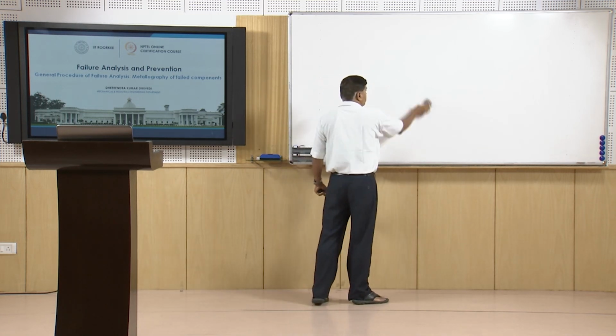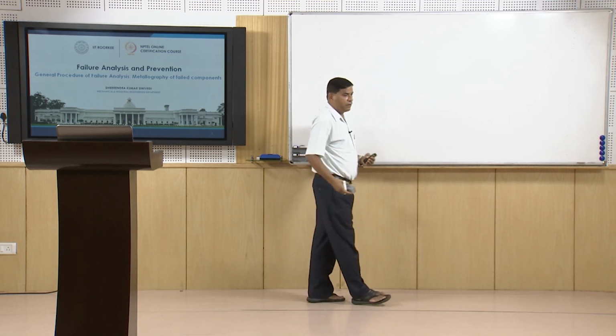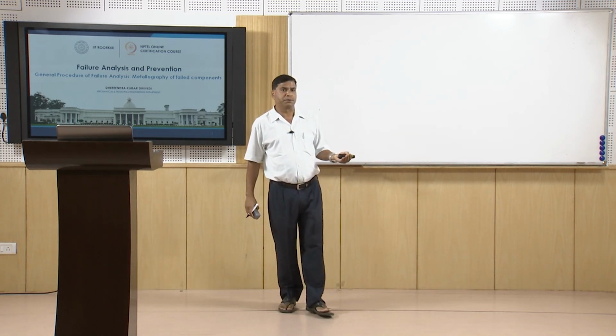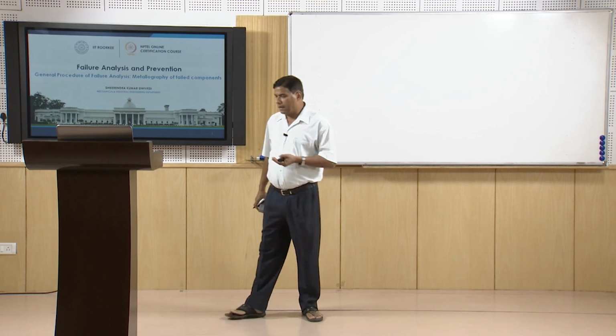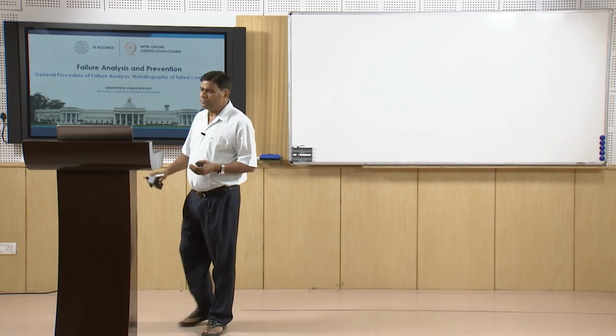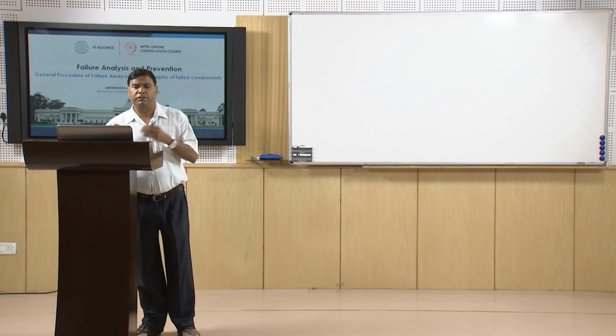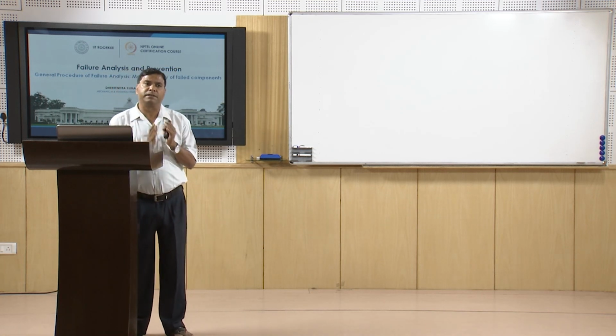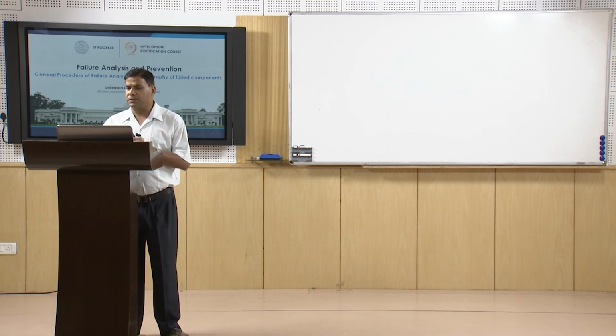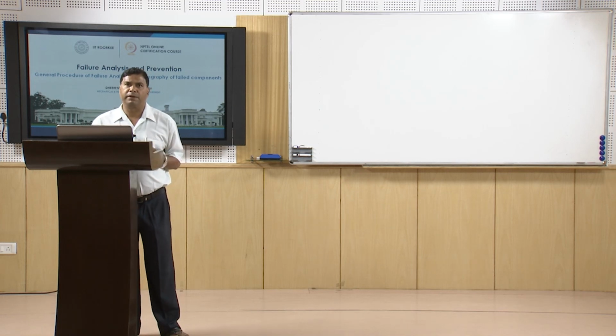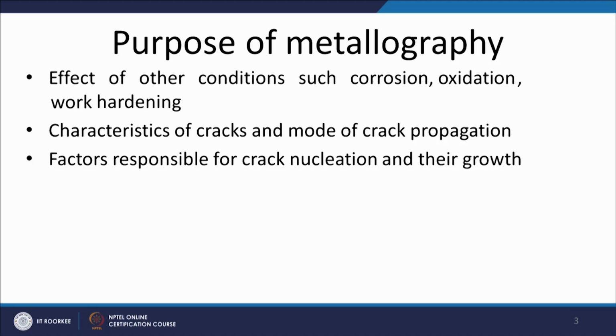So, this possibility of the structural modification due to the high temperature exposure can be identified through the collection of the background information or the service conditions. It will indicate whether the heat treatment was designed or heat treatment has occurred accidentally, and because of which the metallographic changes in the component have taken place.